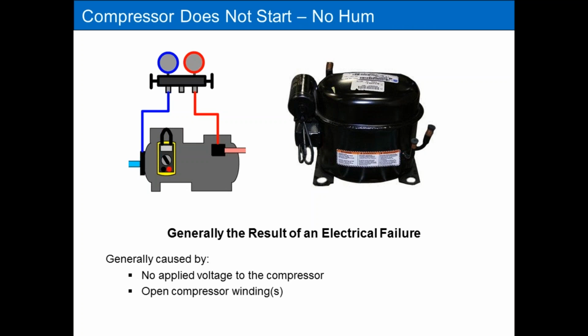If the compressor doesn't start at all, no hum, it's just dead, it's probably an electrical issue, whether it's no voltage applied, you have no voltage to the compressor, or you have an open winding, right? So that could cause that electrical failure. Open winding or no voltage would cause the compressor not even to try to start, no amperage draw, no nothing.